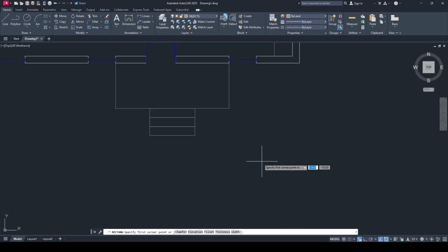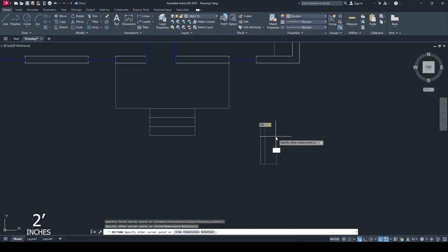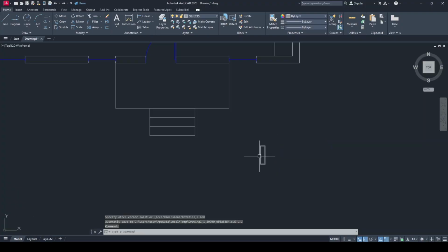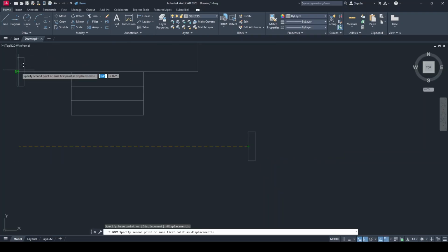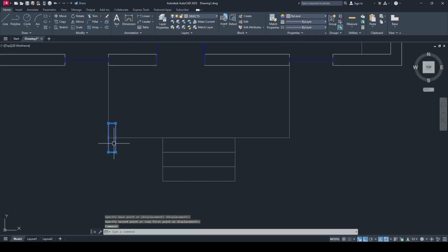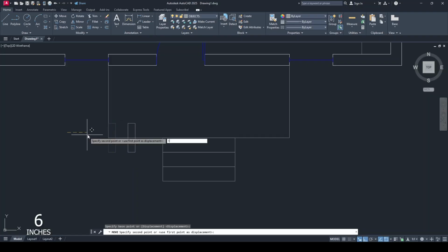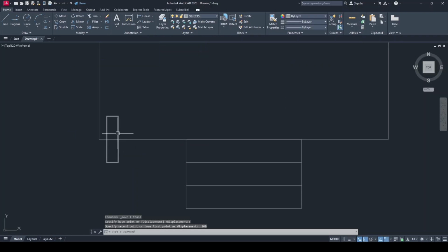Now select the rectangle, click once, point up. For the fins, type 150, press the tab key and type 600, press enter. Click on this one, select move, click on this midpoint, take it to this endpoint. Now select this rectangle, move it this way by 100, press enter. Select this one, copy it, select this endpoint, and then select this midpoint.